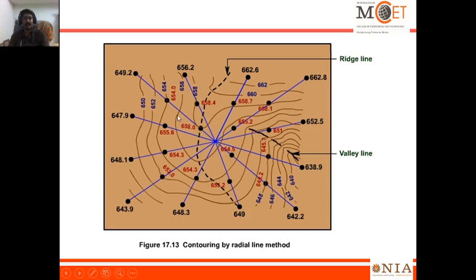On these radial lines I hold the leveling staff and obtain the RL of those points. From the benchmark plus staff reading over the benchmark, you will obtain the height of the instrument at this position. If you subtract these staff readings, you will obtain the RL value of these points. Similarly over all the lines.